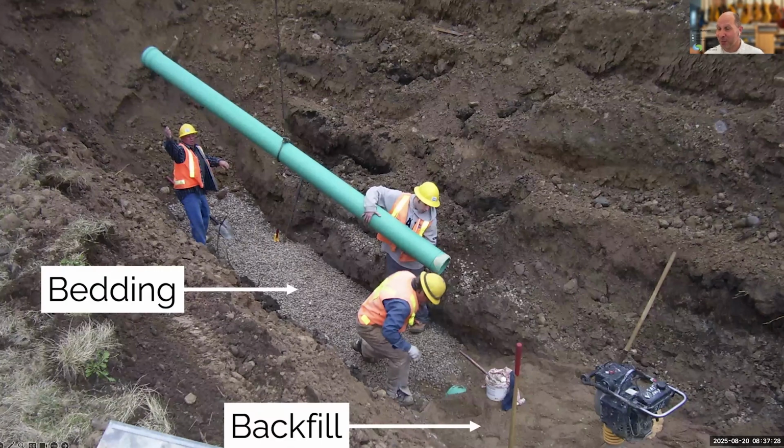So backfill is bringing the trench up to the surface, right? Putting all the dirt that we dug out to make the hole in the first place back in place has to be done very specifically. Typically design specs or instructions from engineers will be very clear about how the bedding's supposed to be compacted in lifts or layers, because you can't just throw 8 feet of dirt into a hole and compact it on the top and expect that to work.